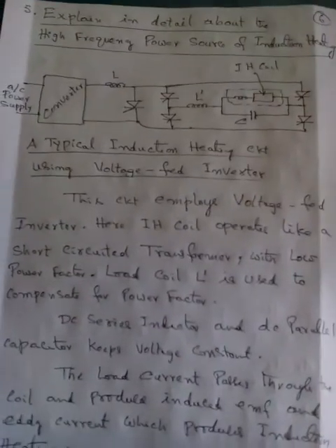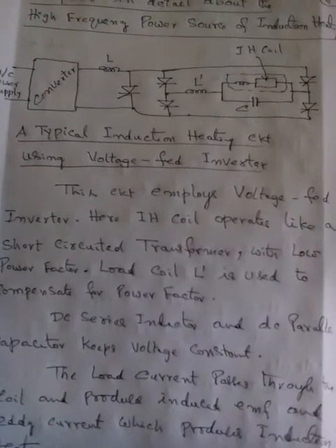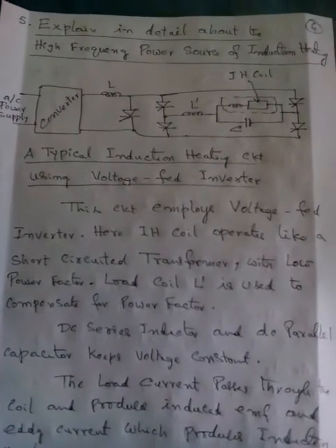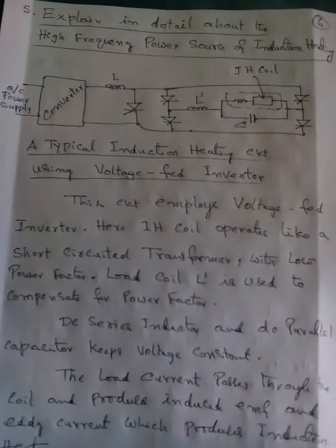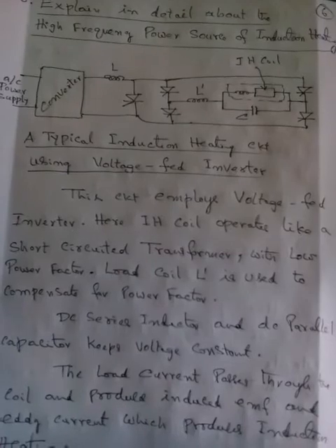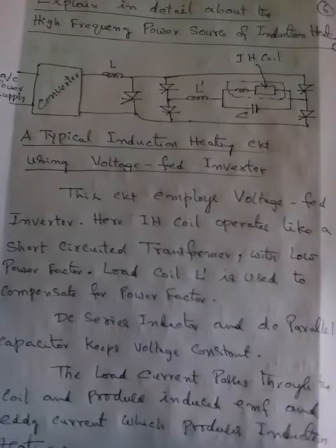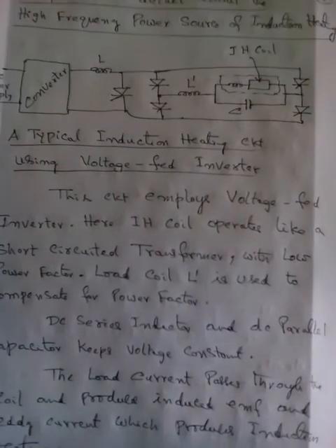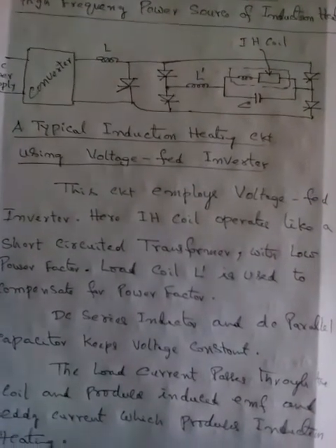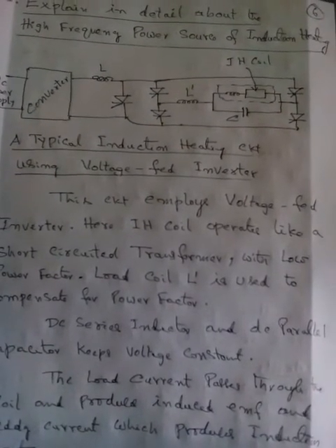Here the induction heater coil operates like a short-circuited transformer with a low power factor. The load coil L is used to compensate for the power factor. The DC series inductor and DC parallel capacitor keep the voltage constant.